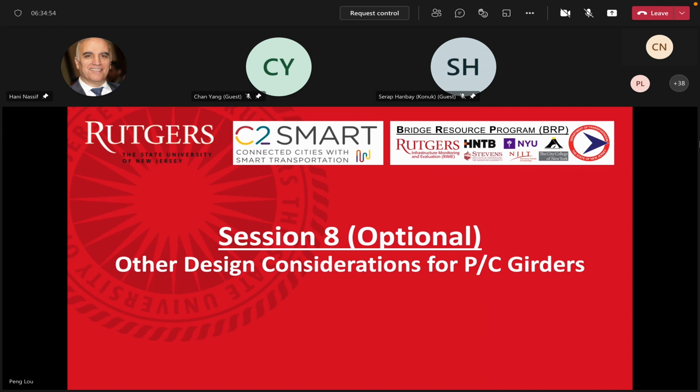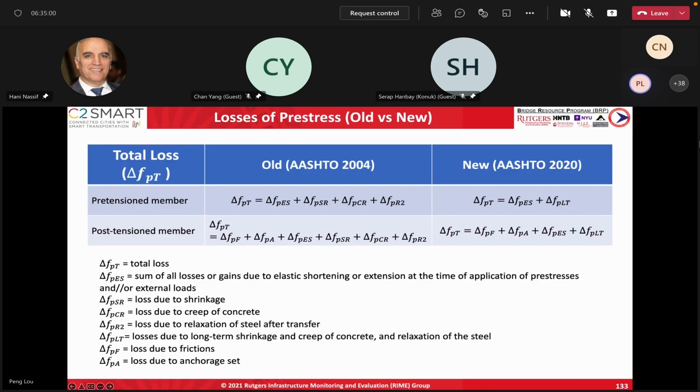Yeah. Okay. So we're gonna briefly talk about these losses, the loss of pre-stress. I think, as Dr. Nassif mentioned, AASHTO has made a lot of changes, especially lately, for different kinds of losses, especially the refined estimate of losses due to shrinkage, creep, and relaxation.